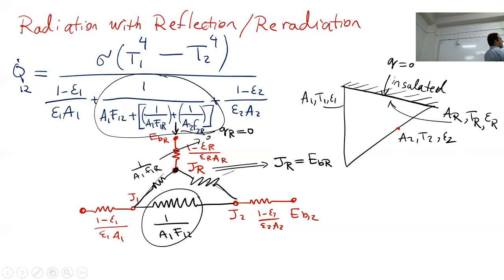On this, we can talk more or do more examples. But bottom line is that it's radiating, the backside is insulated, no heat is added. So really no heat is going through this. So you can ignore this, which almost looks like a black body.